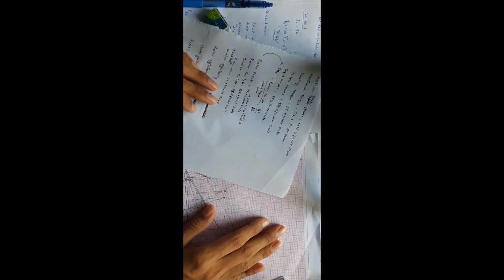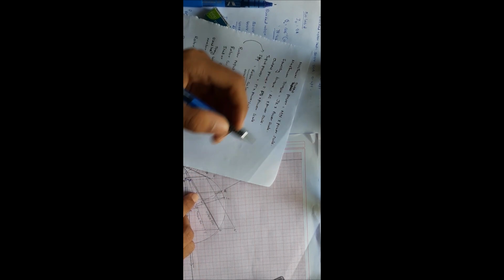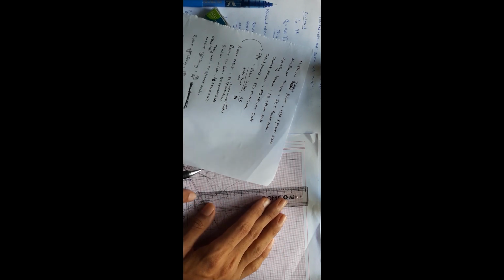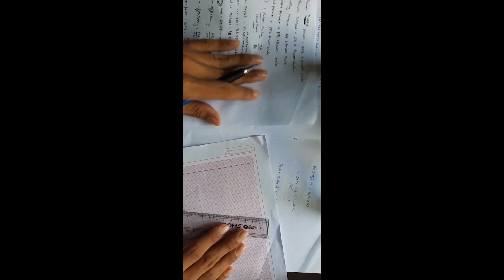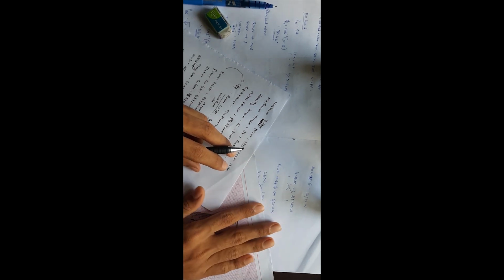After our circle diagram, coming to the final calculations. Here we have got maximum output power. So we have to check the output line. Here the maximum output power is MN. This is our maximum output power. So here we'll get some length. It will be almost 3.3. So we have to multiply MN with our power scale, whatever we had calculated.